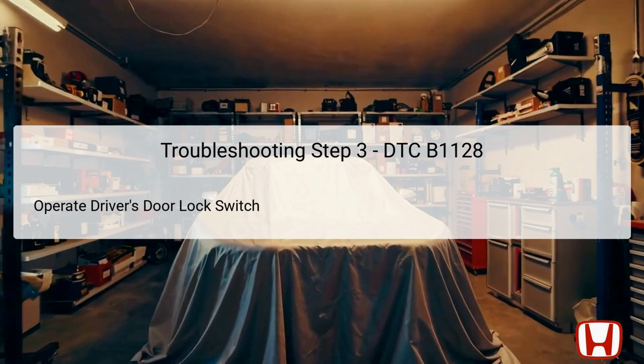Repeatedly using the switch during this step can help identify issues such as a stuck button or a loss of signal. By doing this, you can observe any erratic behavior from the switch, which could confirm whether the problem stems from this component directly. If issues persist, this would warrant further investigation into the switch and its associated circuitry.